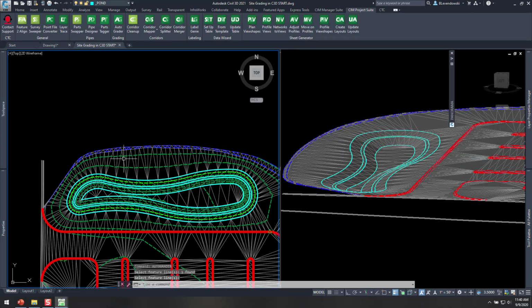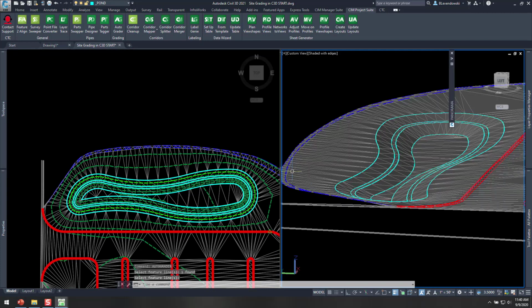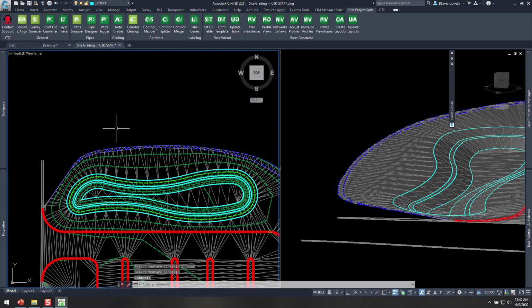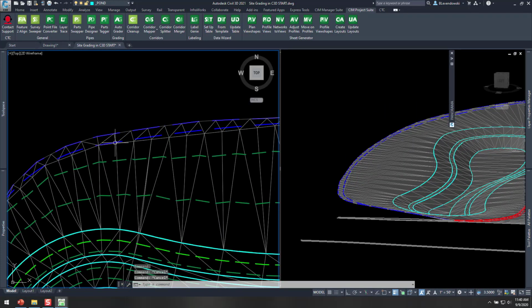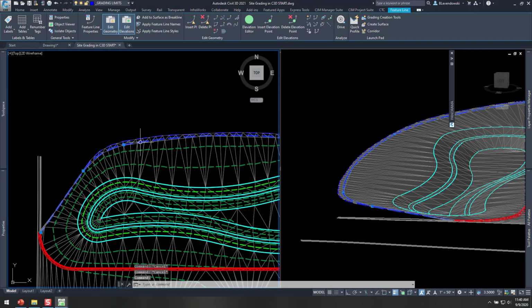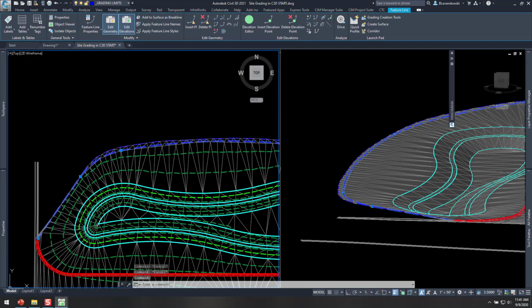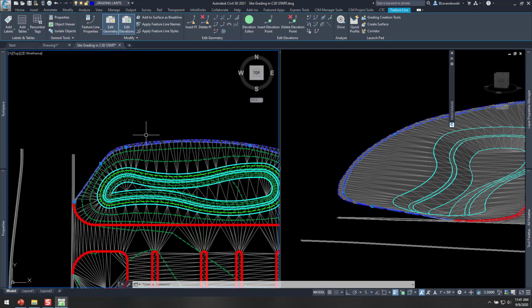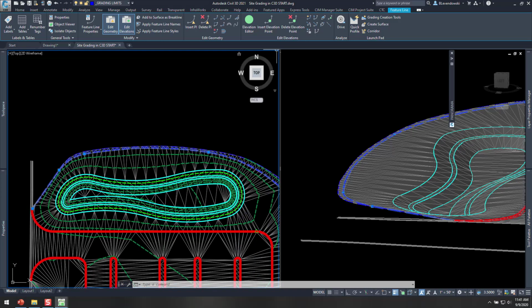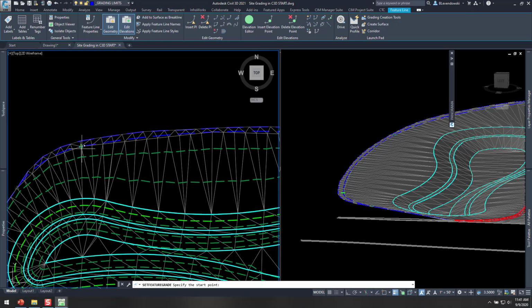the surface. Now that's not much of a berm. You can see it right here. So what we can do is we can bring that up a little bit. And this is the kind of process you end up going through. You try some preliminary grades, then you move things around. I'm going to instead use this set elevation or grade to points. I'm going to pick this one again.